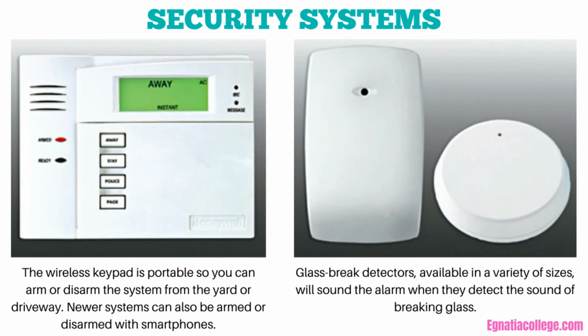The instructions furnished with all security systems cover the installation requirements in detail, alerting the installer to Canadian Electrical Code (CEC) regulations, clearances, suggested locations, and mounting heights of the system's components. Always check with the local electrical inspection authority to determine if there are any special requirements in your locality for the installation of security systems.